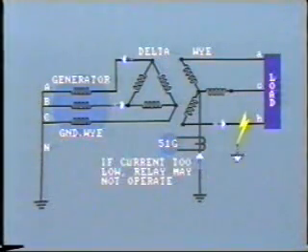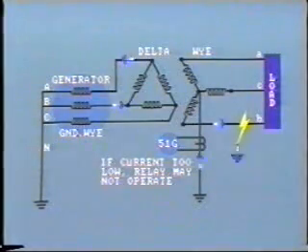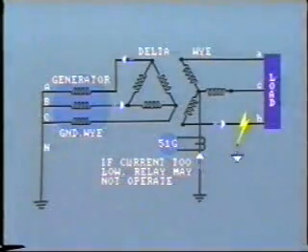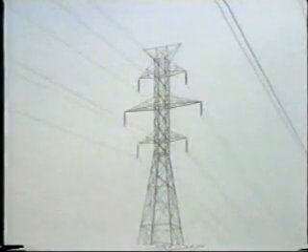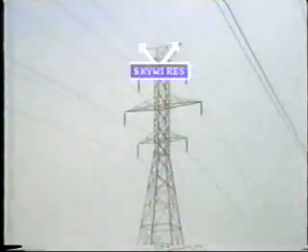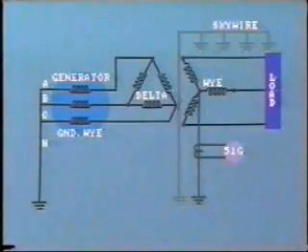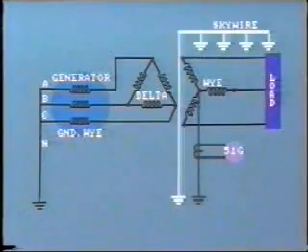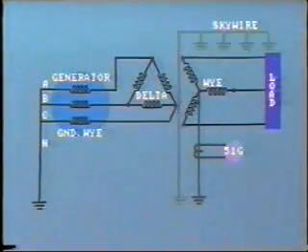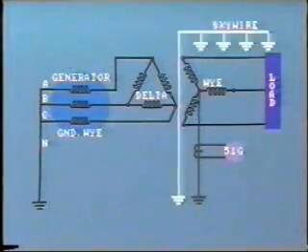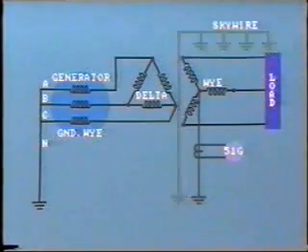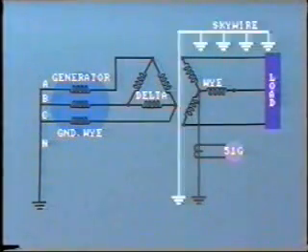Note that if the level of fault current is too low, this relay may not operate at all. But often another path is provided. For example, with high voltage transmission lines, the steel towers are connected together at the top by a bare ground wire or sky wire. This ground wire goes right back to the substation structure, which is, of course, grounded to the mat. Consequently, the ground wire provides a parallel path to current flow through the earth.